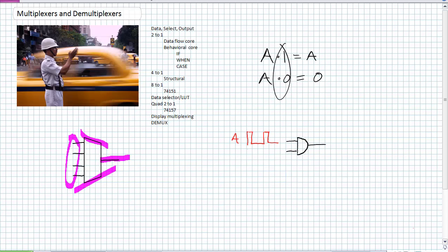Okay, so here's an AND gate, and it's got incoming digital data, A, on one of its inputs, and on its secondary input here, we're going to place a 1. So what happens to the output? Well, it looks exactly like A. Now we replace that secondary input and put a 0 on it. Regardless of what's happening to A, what happens to our output? Nothing. Okay, 0, straight 0. That secondary input is acting like an enable.